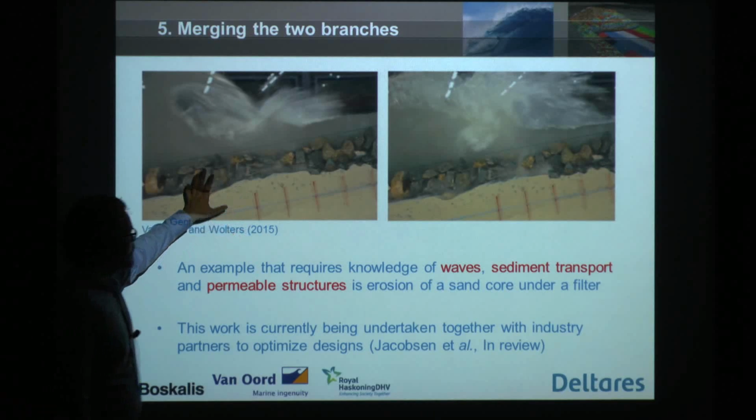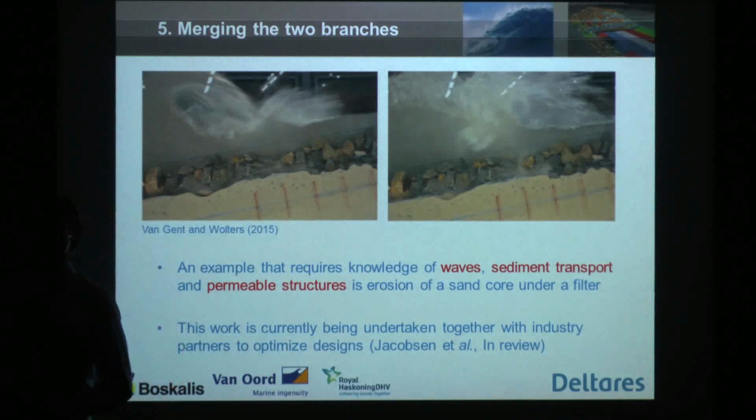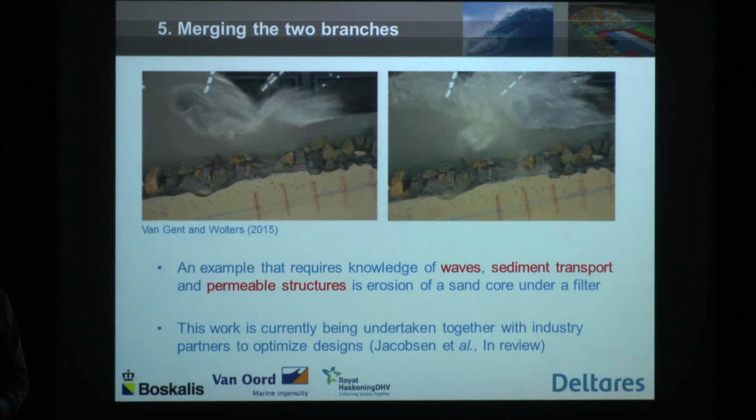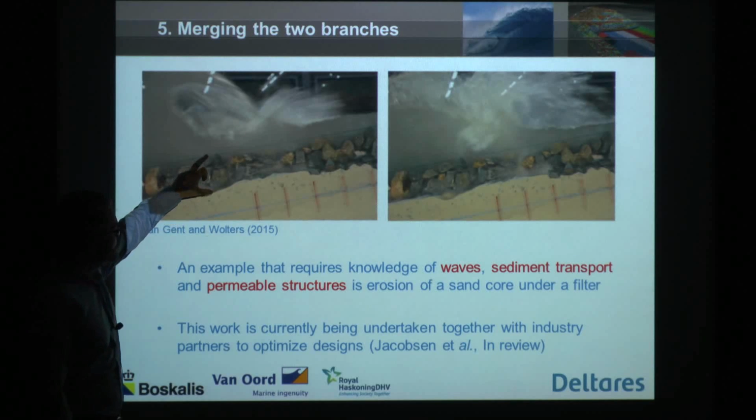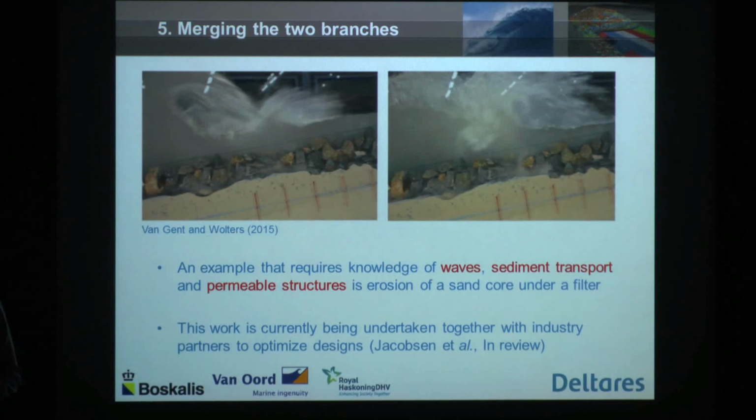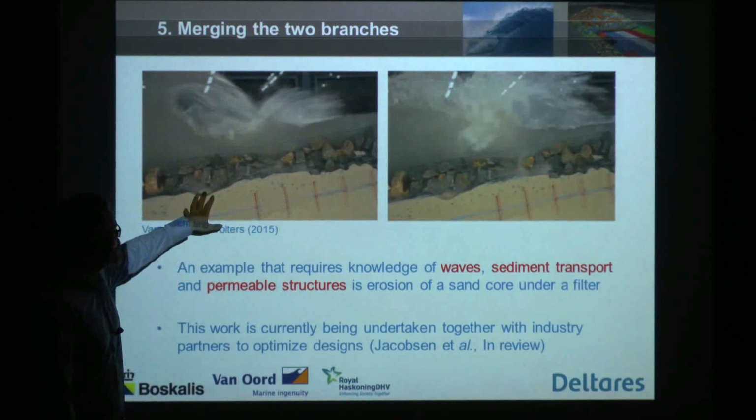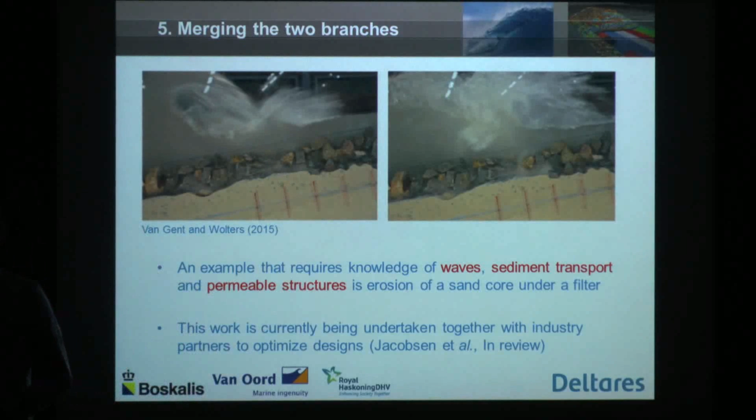And the study starts with what we call an open filter. There's a growing interest in trying to keep designs as low cost as possible and to push the limits of given design rules. So how thin can you make a stone layer on top of a sand core is the base question, such that we still have it be stable, or the structural integrity of the structure will remain over the next 50 years. So it's a study about how the sand moves inside the structure under wave loading.